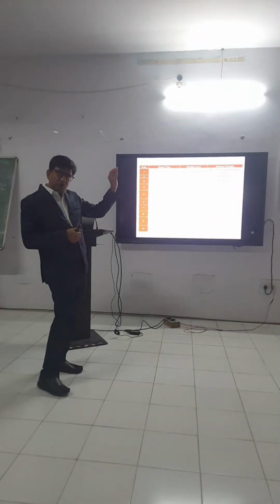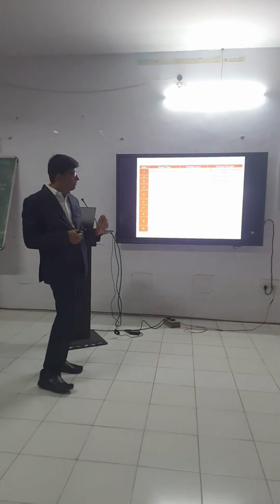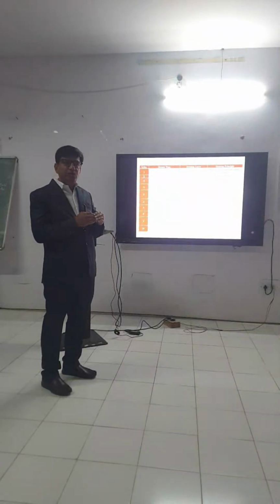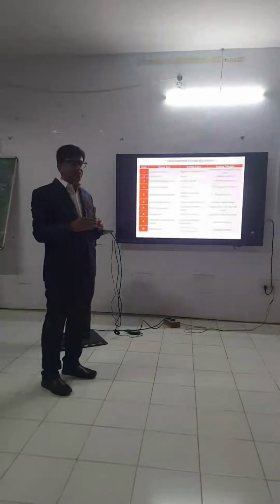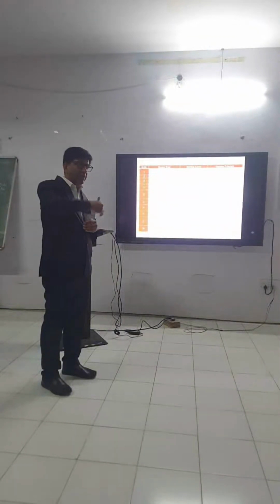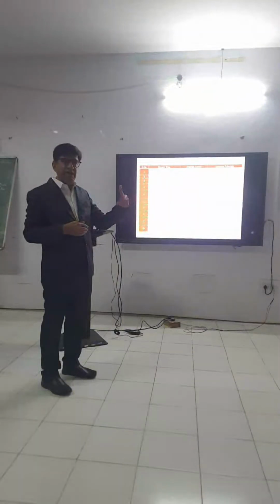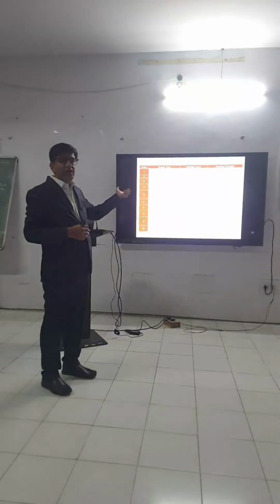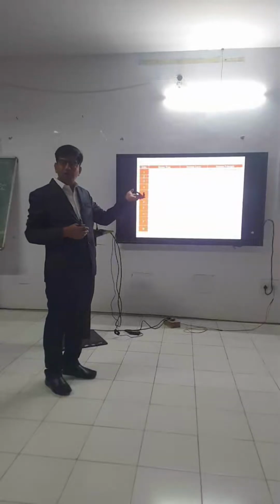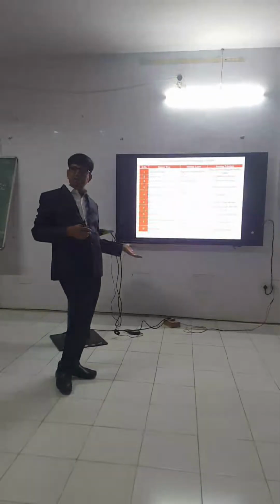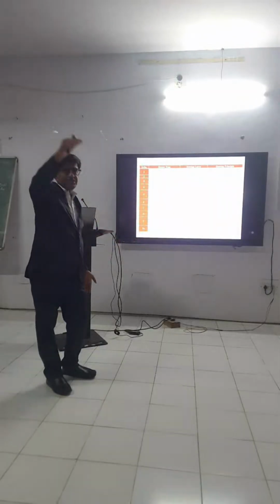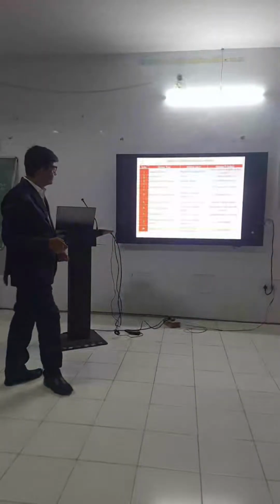Due to mass loading, your frequency will be shifting down. But if you are using polymer, then due to the stiffness, it will increase your frequency. So sometimes you have an increase in frequency, like that is the case of resistance. Your resistance increases or decreases based on the type of gas. Here your frequency will increase or decrease based on the type of sensing layer. If it is metal oxide, it will shift your frequency down, or if it is polymer, it will increase your frequency up.